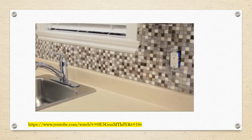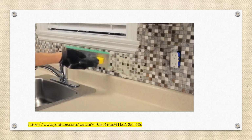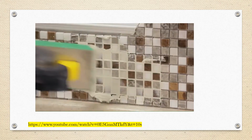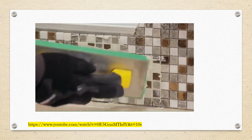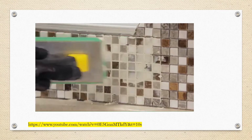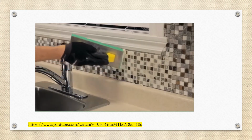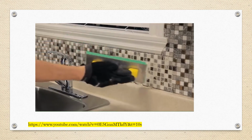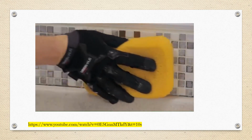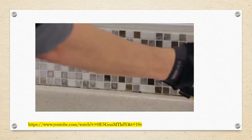Using a rubber grout float, work the grout into the joints. Hold the float at a 45-degree angle. Apply the grout section by section on a surface of 10 square feet at a time. Don't apply grout to gaps separating the tiles from another type of material, like the countertop or cabinets. Remove excess grout. Then clean the surface with a damp sponge, working diagonally over the tiles.